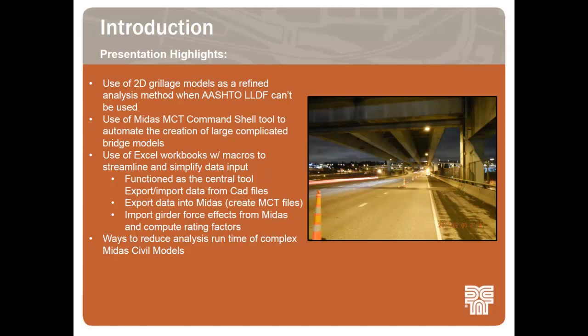The combination of the Excel workbooks and the MCT command shell can allow for easy data input into an Excel table and then use a macro to create the MCT file to streamline the whole process. I'll also talk about ways to reduce the analysis runtime of these complex and large Midas Civil models.